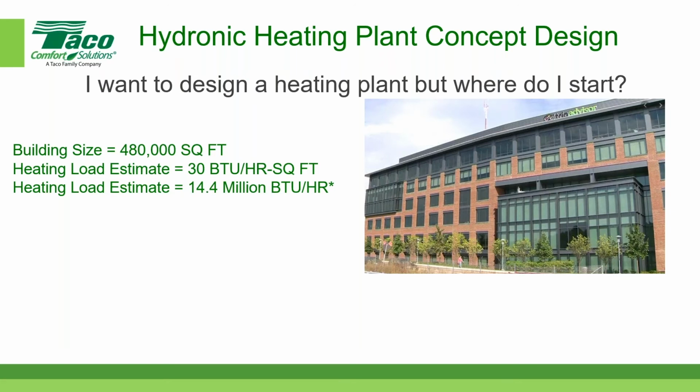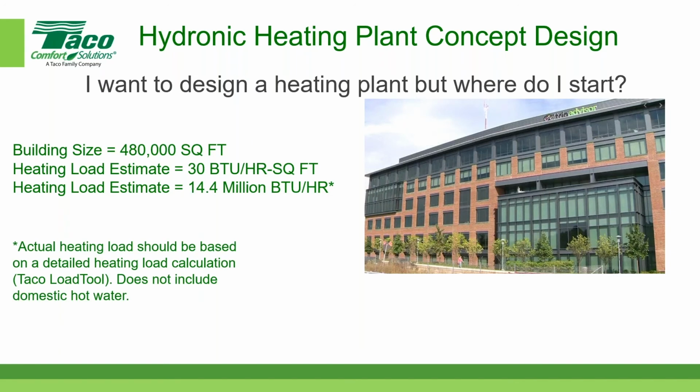And if you notice, I put a little asterisk here because the actual heating load should be based on a detailed heating load calculation. You can use the TACO load tool. And the other thing is that for today's discussion, the load does not include any domestic hot water. So our hydronic heating plant is not going to be responsible for domestic hot water, just for the building itself.